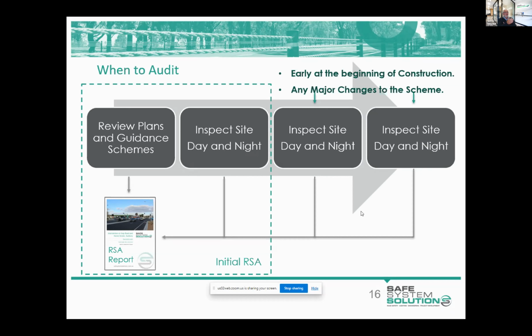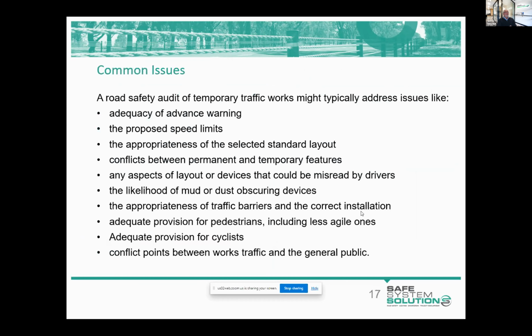It's so important that, with the initial road safety audit, at the beginning of the construction site, and with any major changes to the scheme, we do a review, but we also do a night inspection, both a day and night inspection, to understand what the conditions are in both those situations. It's so important. I'm sure, Ken, with the other audits, Jamie and anybody else has spoken, that day and night requirement is so important.